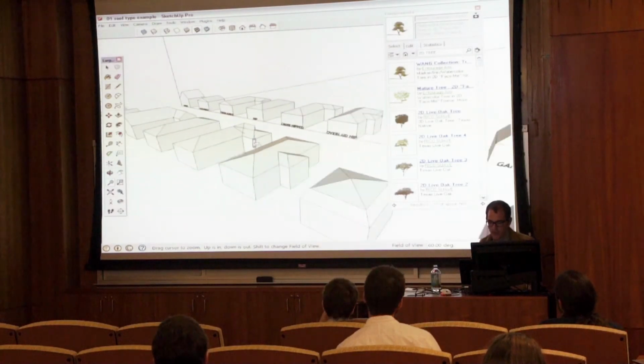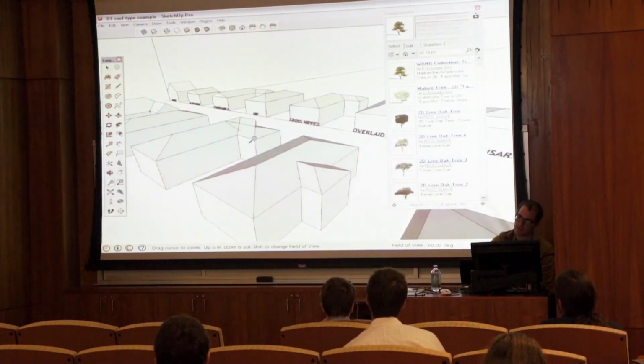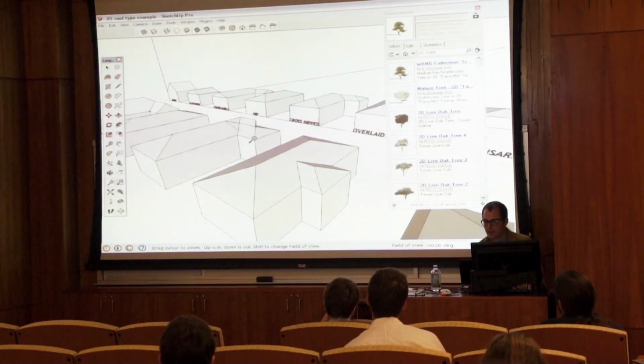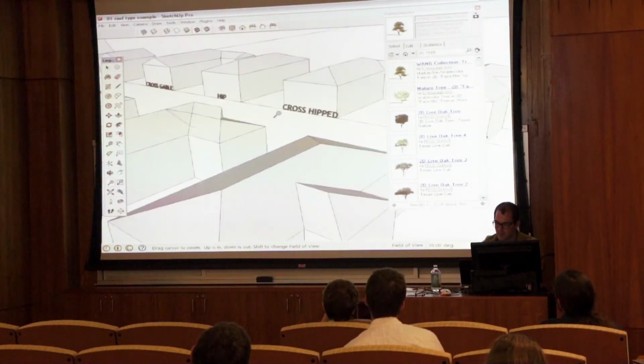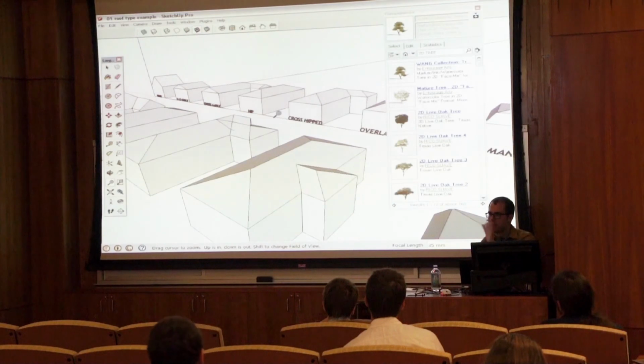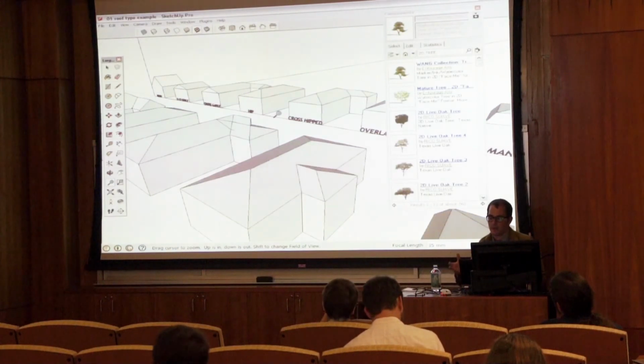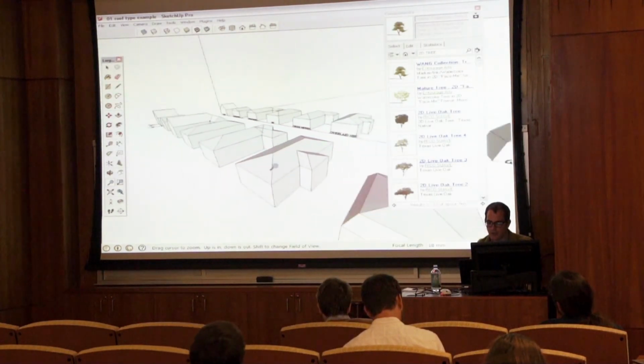If you prefer working in photography focal length, let's say you want this to be 35 millimeters, you can type in, again, this is all within the zoom tool, 35 and then lowercase mm, sorry, and see how it changes the name from field of view to focal length? This will simulate 35 millimeter focal length. You can also hold down shift and zoom in, and that's actually going to adjust the focal length.